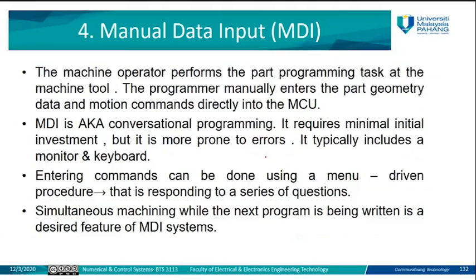So the programmer will manually enter the data or the geometry, the point, the action, the motion command, and so on, directly into the MCU of the CNC machine. In this case, the programmer does not need to write the program first, and does not need to use a computer or CAD/CAM programming. Maybe this will be more useful when you develop a simple program, like 5-line or 10-line programs.